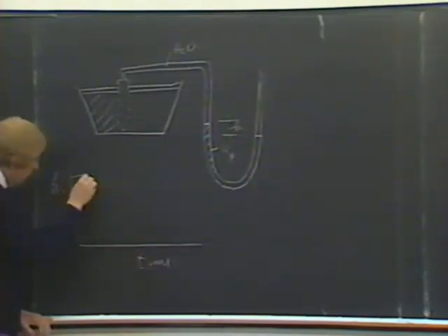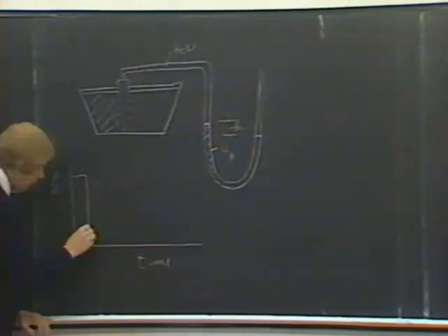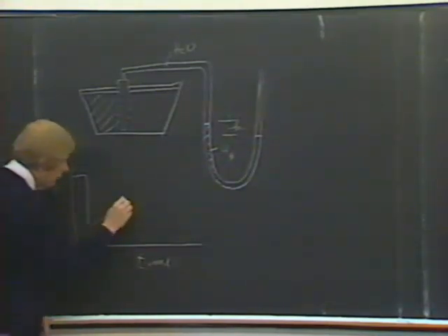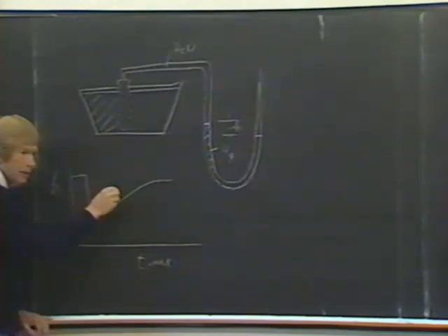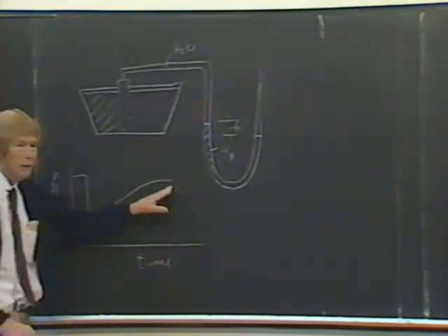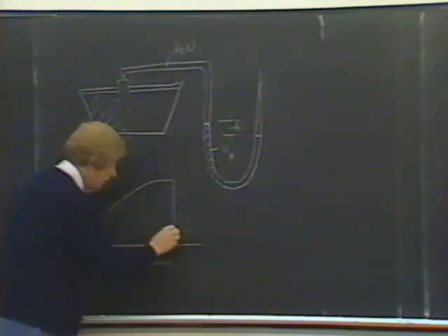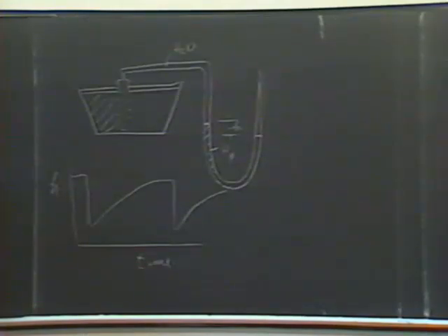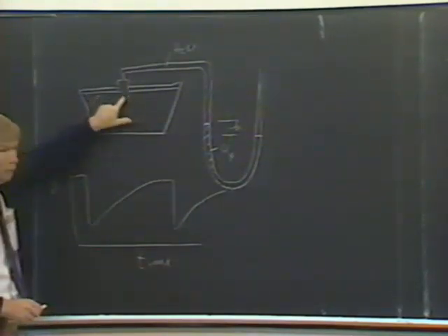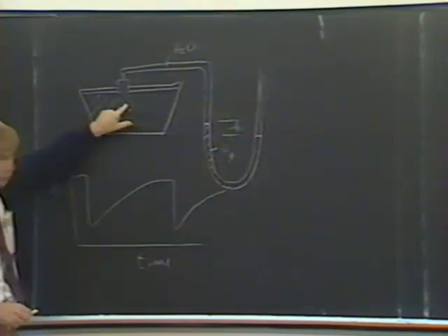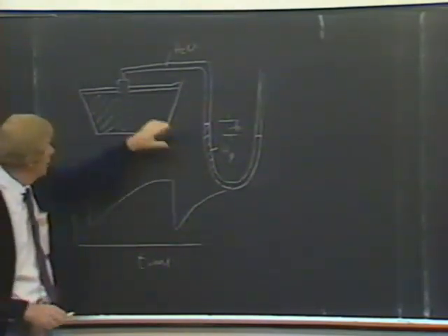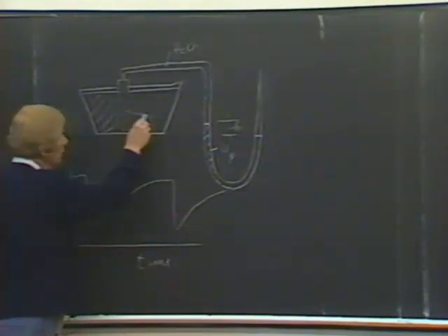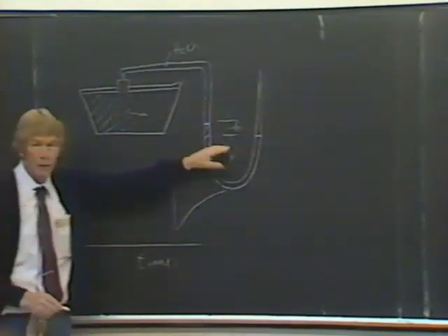indicating that the soil, after it was stirred and allowed to stand for a while, was taking water from the porous cone. The soil was taking water from the porous cone so as to cause this difference, and it did it against a pressure. So the soil was taking up water. Do you follow me? And when you stirred it, it released that water again, and then gradually it would take up water again. Now, this is a curious phenomenon. You know, it's quite an unusual thing.